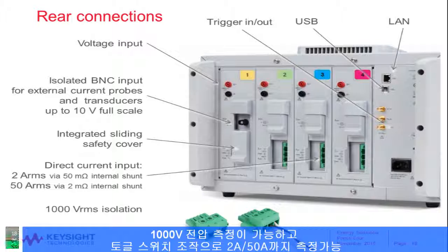Or I can slide this little door and it exposes this green connector, and now this is like an ammeter that you'd find on a voltmeter, on a DMM I mean, and that means you can run the wire in and out of this connection, and it has an internal current measurement system, which is extremely accurate. So this is for ease of connection, and this is for highly accurate current measurements.